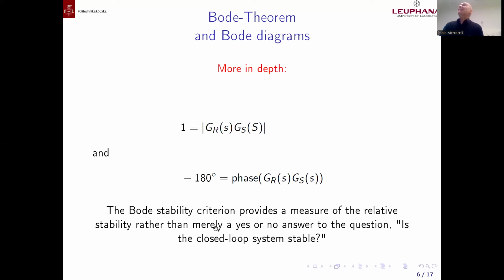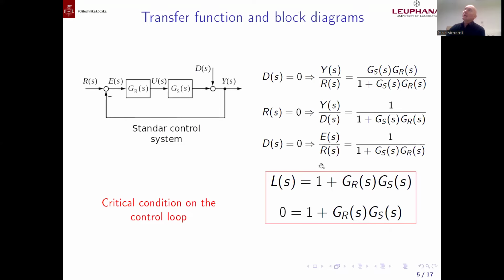Let me go ahead. It seems to be complex, even though we are dealing with a complex value. This means we have already characterized mathematically the critical situation. Then I will tell you a little bit more in depth about the denominator, because the denominator states the position of the poles. We say the poles in the nomenclature of the transfer function.